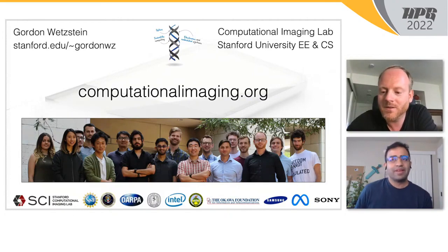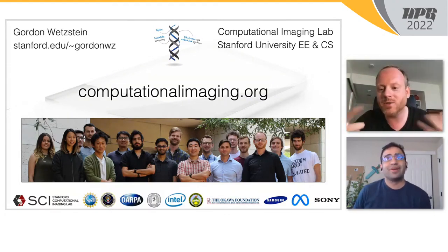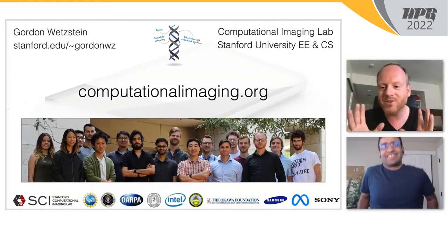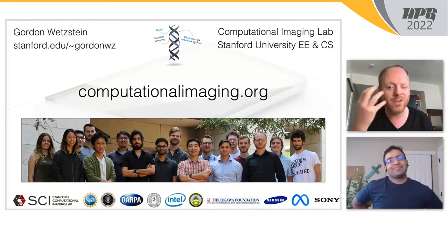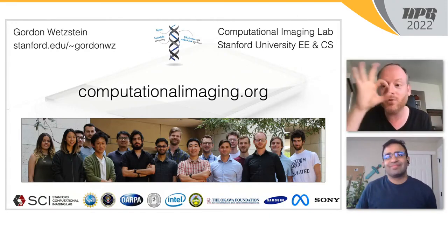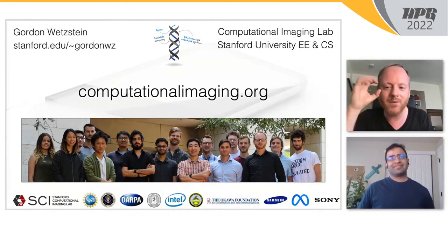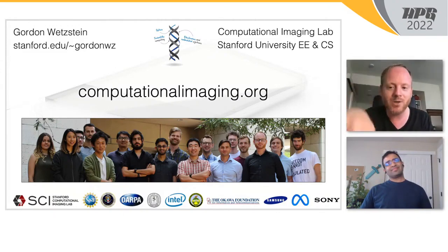Well, while he might step up to the mic, let me talk about the next question. It says, okay, I mean, I think I know what you're talking about, but when you think about eye tracking, there's a couple of different aspects to it, right? If you think about a single eye, typically, first of all, we want to estimate the pupil and maybe the glints. From that, we get a model, we get the gaze direction. And so indexing from the eye tracker into the pixel of a display is a challenge because you need to be robust for slippage and so on and so forth.